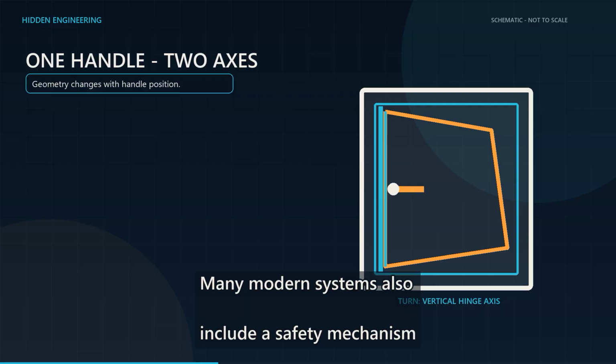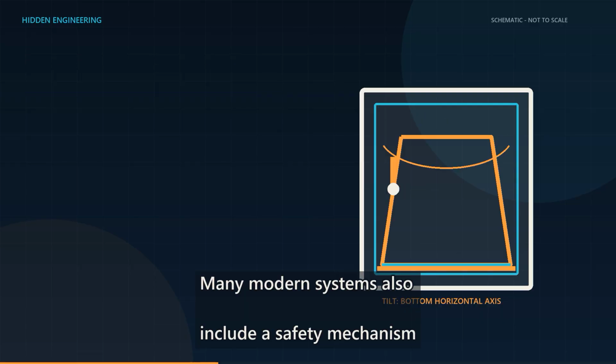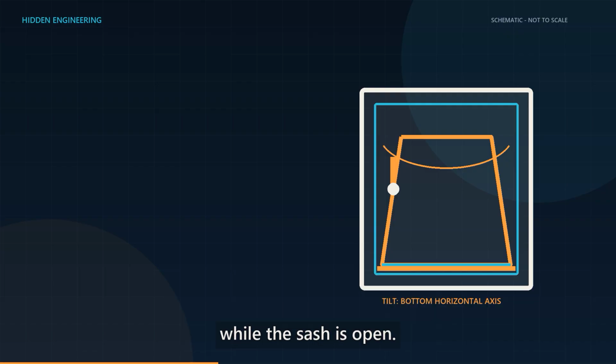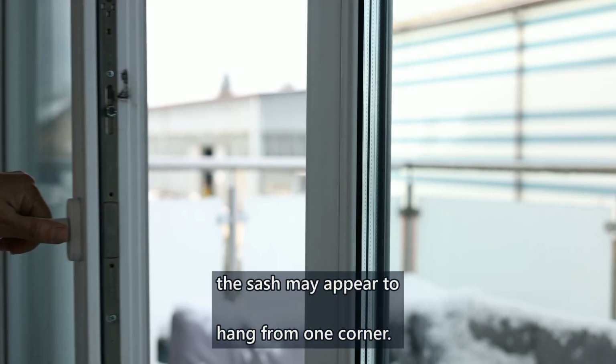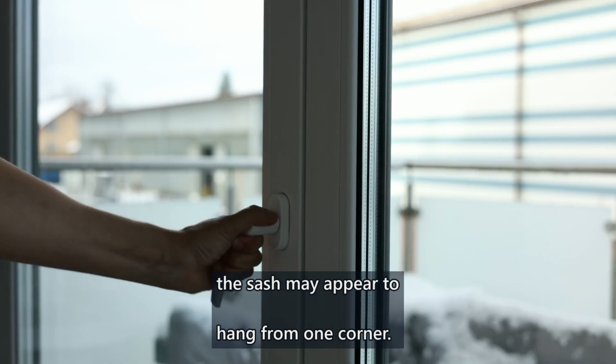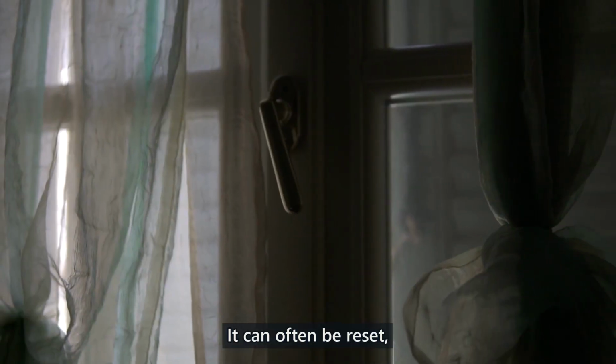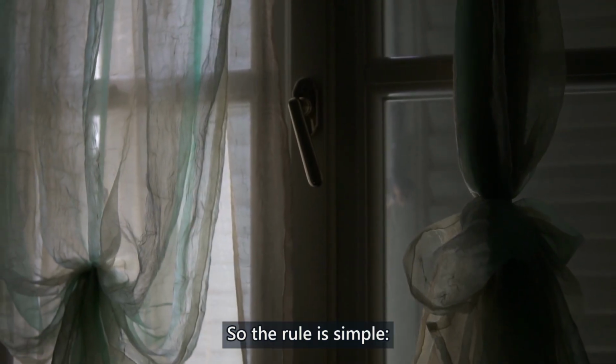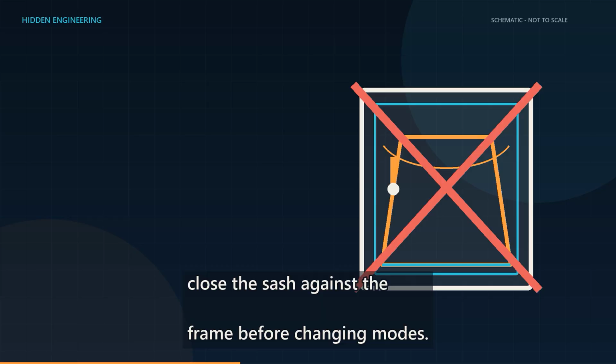Many modern systems also include a safety mechanism that helps prevent the handle from selecting the wrong mode while the sash is open. Without that protection, or if the window is operated incorrectly, the sash may appear to hang from one corner. It can often be reset, but forcing the handle can damage the hardware. So the rule is simple. Close the sash against the frame before changing modes.